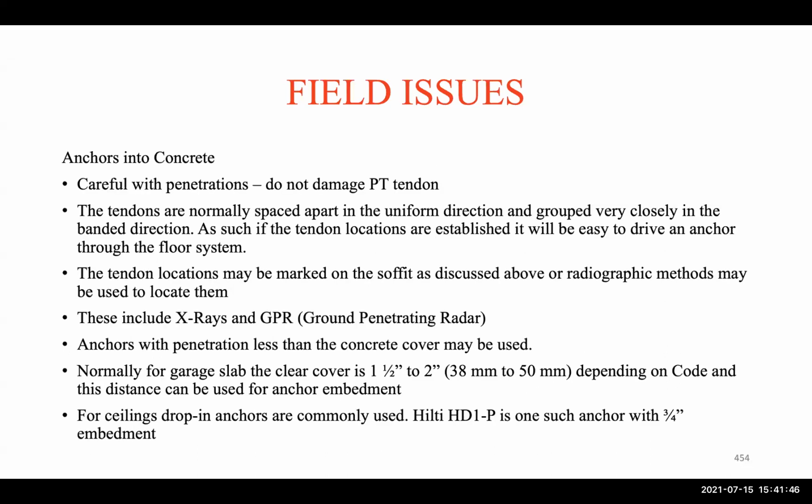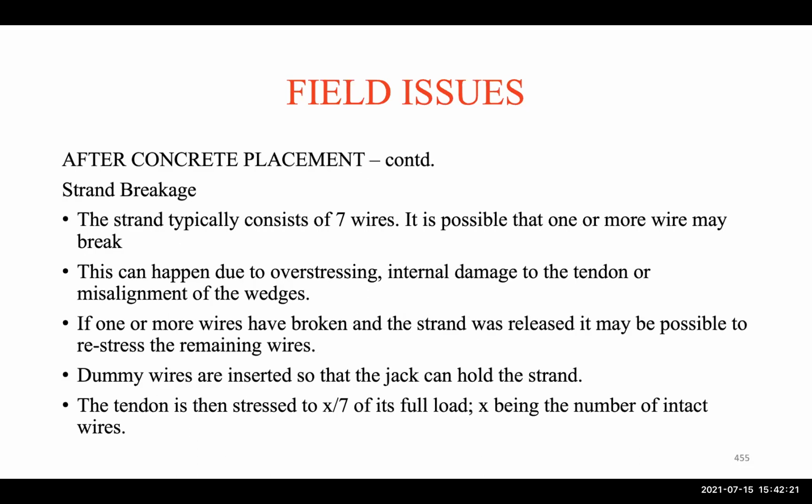And then of course anchors into the concrete, for whatever reason, used to hang something from the concrete, could be done in different ways. If the layout of the PT is there, then you know what to do. Or there could be inserts within the floor. So when they cast the floor, they can have inserts for certain things to hang. Okay, but this has to be studied in detail, architecturally. So those can be used after the building is occupied.